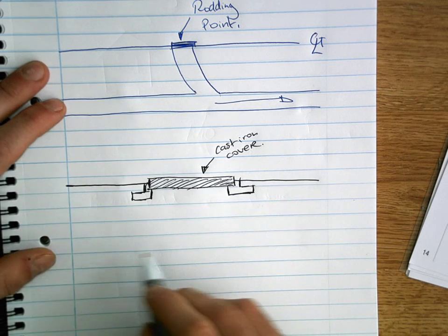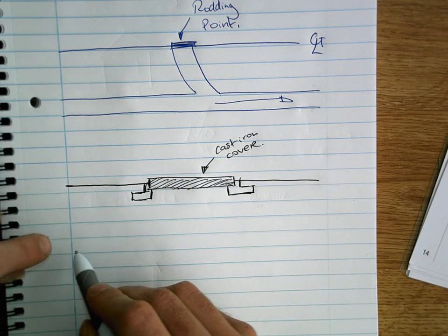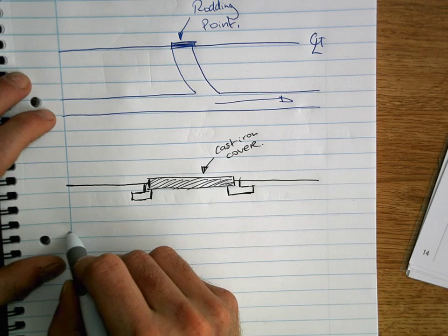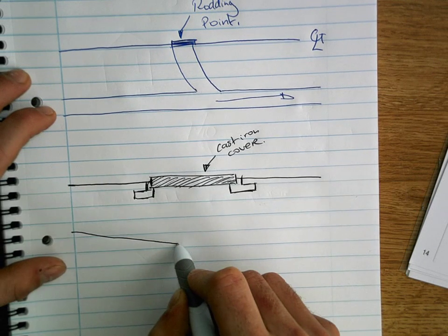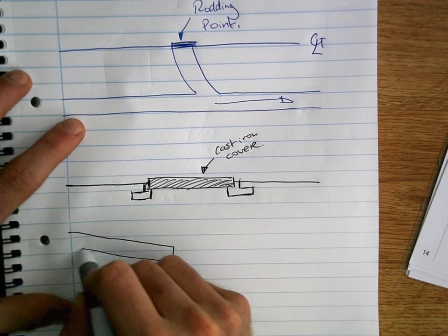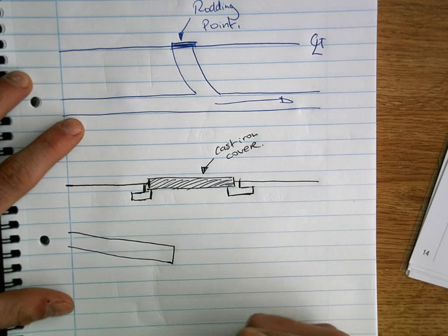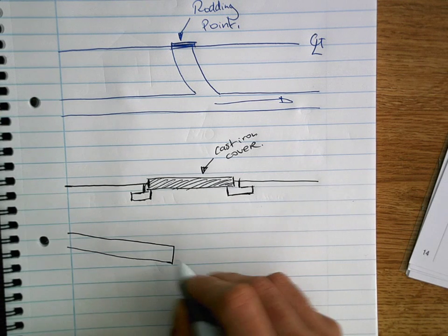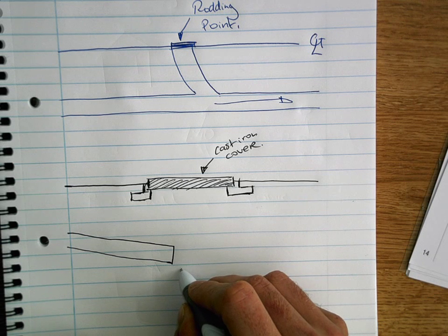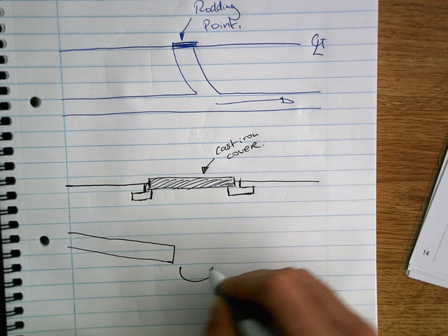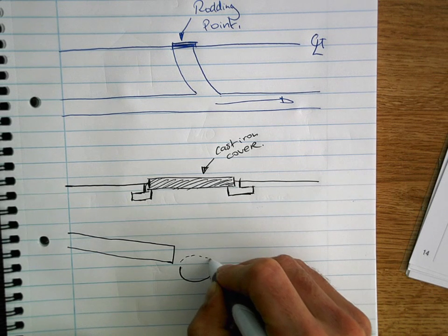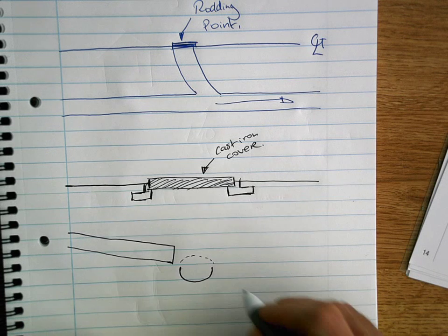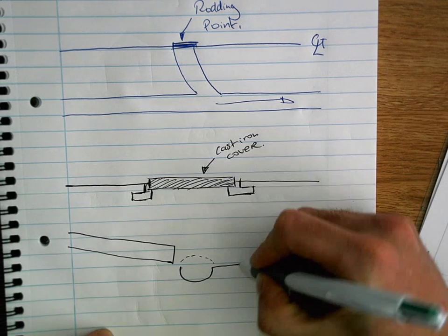So what's happening underground is the wastewater pipe that we drew earlier on in part A is coming from the house, and it's going down the slope of 1:40, and it's flowing into the main system. Now the main system is obviously running perpendicular to this drain that came down, so a cross section of that might look something like so. Then we're going to encase that within our manhole.